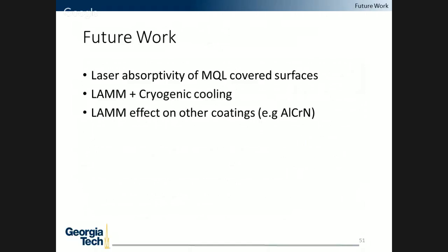Another place that could be further investigated: it has been shown that in conventional scale turning with cryogenic cooling, cryogenic cooling can greatly reduce tool wear. This is yet to be investigated on the micro scale. If cryogenic cooling could be focused on the tool instead of spreading all over the workpiece, as was seen in our experiments, it could be beneficial to the tool as long as it does not affect the workpiece.